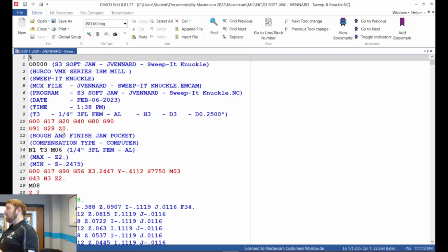I had that added to our Mastercam post because I got tired of students breaking tools because they were setting them off their tool setter down here on the right side of the vise, and then their start point was over here with the part that's in the vise, and they'd hit go, and the machine tried to go rapid from there to the start position, and it didn't know it needed to come up and move over. Rapid tries to go in a straight line. So just think about that. That's basically what would happen. Tool gone, vise has a big notch in it, or the part has a big notch in it, depending on where you're at.